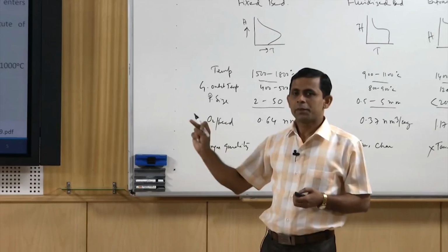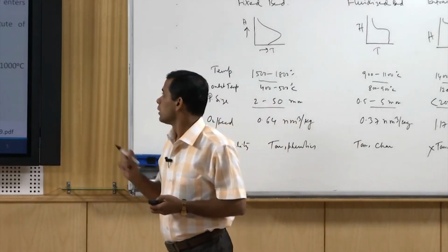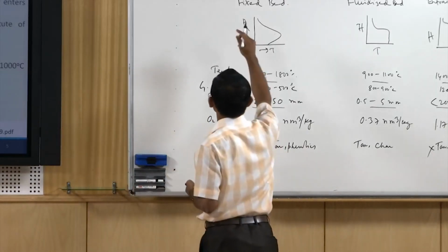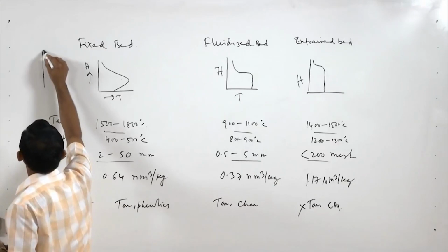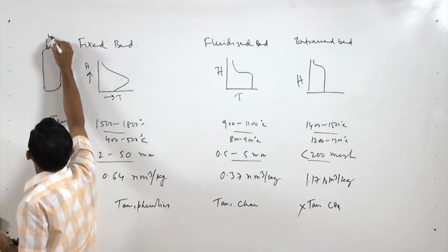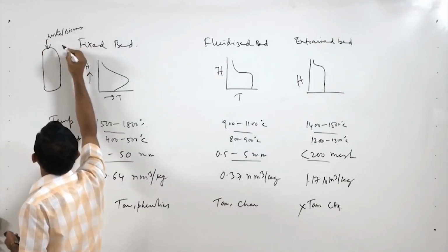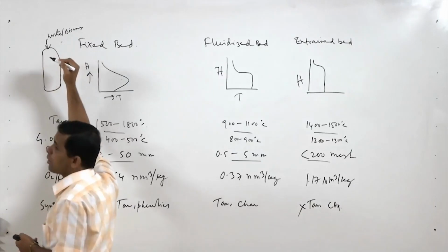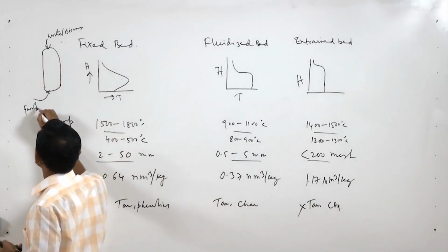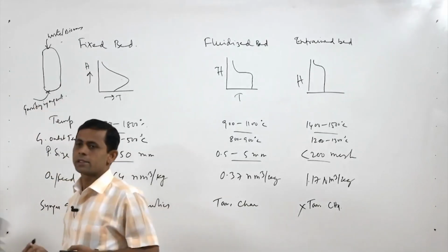The updraft gasifier was developed in 1976 by Georgia Institute of Technology, and in this gasifier, just like the fixed bed gasifier for coal, the material, waste or biomass, is put from the top and from the bottom the gasifying agent. This can be oxygen, steam.